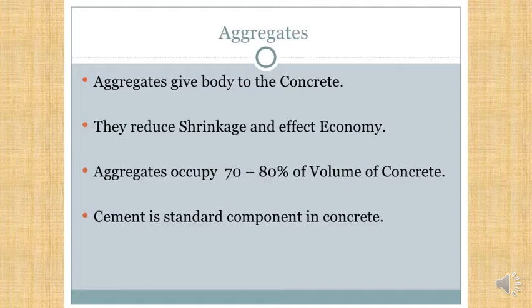Now, the other thing with aggregate, it does actually give strength to the concrete. The cement is holding the aggregate together in a matrix, and that is where the strength is. Cement does not have strength in and of itself. So if you can imagine you had some glue, and I told you to make a figurine out of glue, to make a little model man on top of your desk, it's not going to be very strong if you don't mix that glue with sand, with an aggregate, because the glue itself just holds particles together.